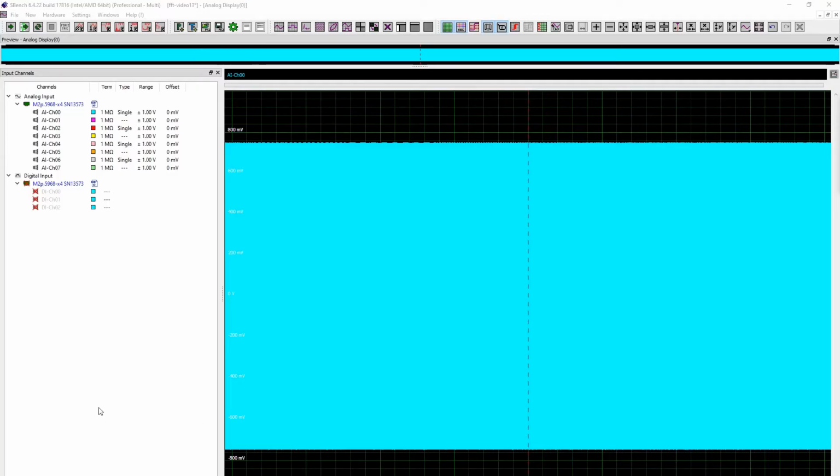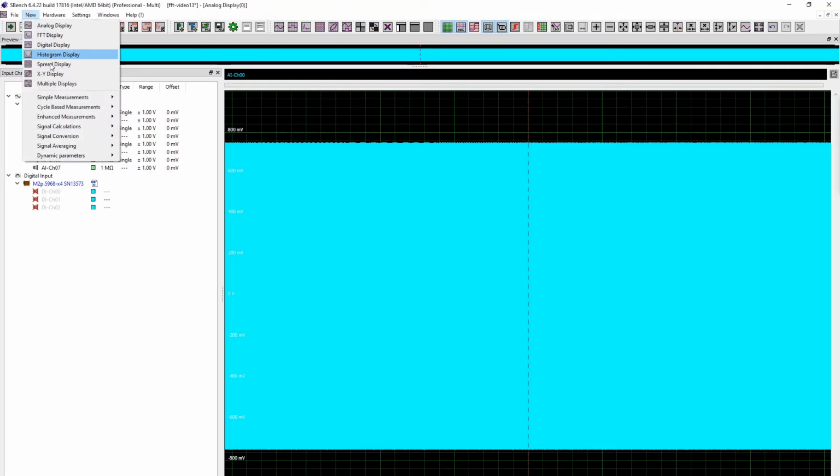In this video, we're going to calculate an FFT signal to show you how to generate a complete new signal with a calculation function. Click the new menu and choose Signal Calculations to see a choice of different calculations.